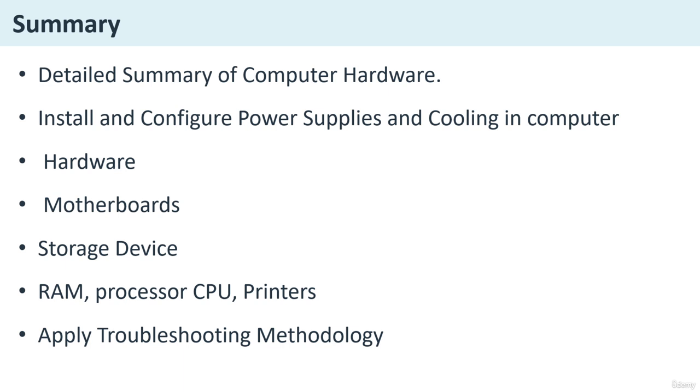Now, installing the motherboard. This is very important. First of all, prepare the case. Install stand-offs, like small screws that lift the board. Second, align the motherboard. Match screw holes with stand-offs. Number three, secure the board. Use screws to fix it in place. Number four is connect power cables. That is 24-pin and CPU power. Number five, install RAM, CPU, and storage before powering on.